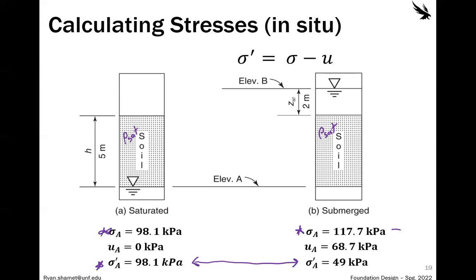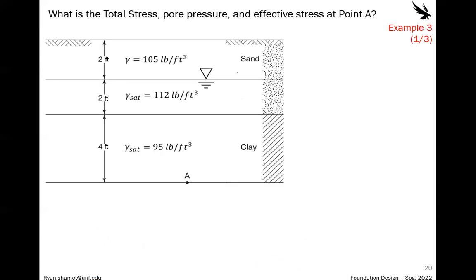So again, this is just a single soil column, but most of the time what we'll see is an example like this where we have different stratigraphy. Stratigraphy is different soil layers with depth. As a geotechnical engineer, your first job is going to be to define these soil layers and then be able to do the analysis on it. This is a common example like in Florida where we have sand, we have a water table right here, and then we have clay underneath that.